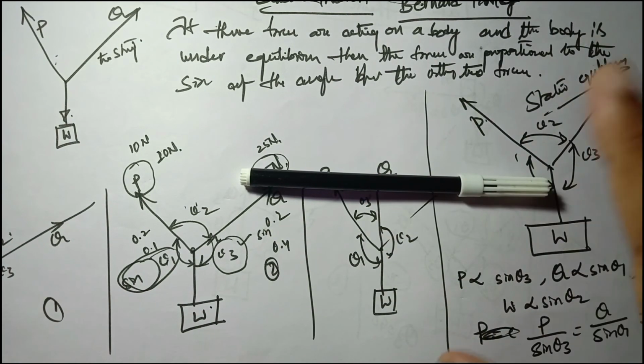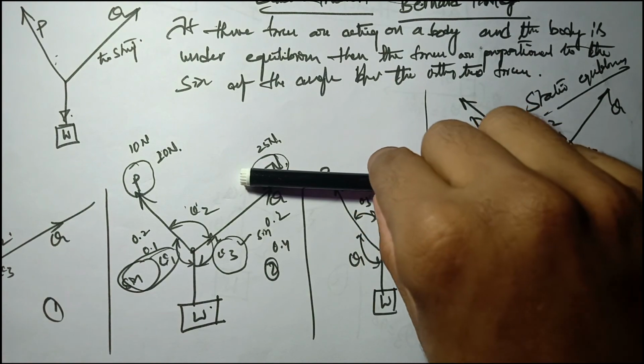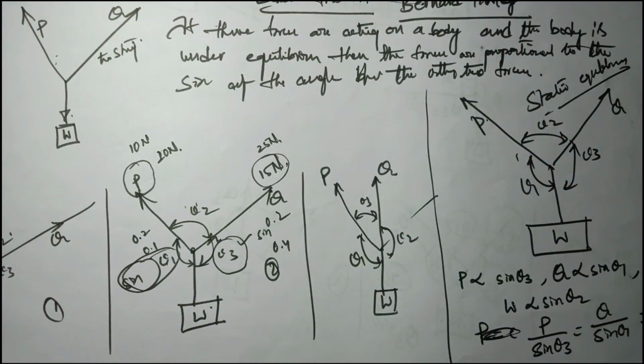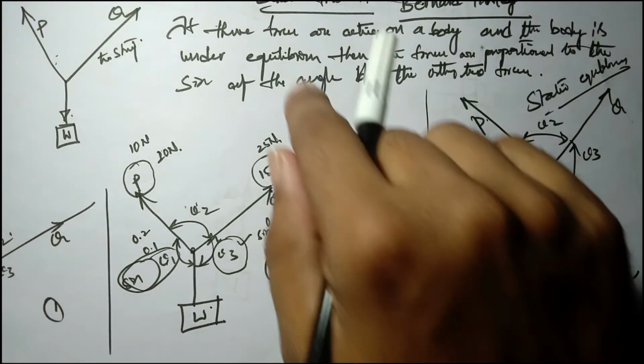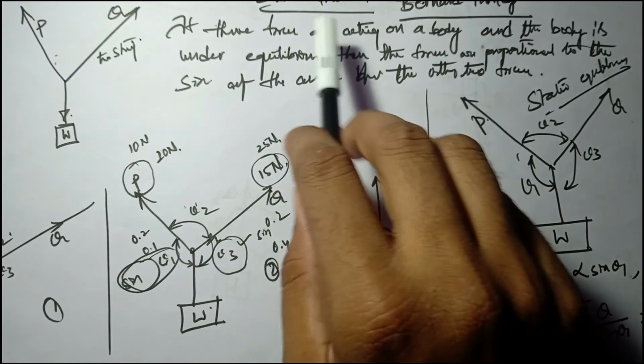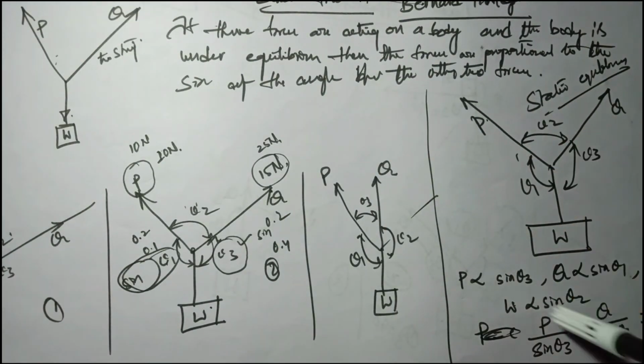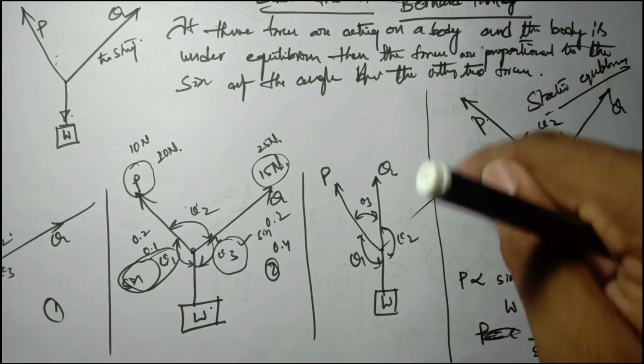So whenever there are three different forces acting on a body which is under static equilibrium, we can apply Lamy's theorem. Using Lamy's theorem can simplify a lot of problems, because these are simple equations which relate three different forces just by using the sine of the angles between them.